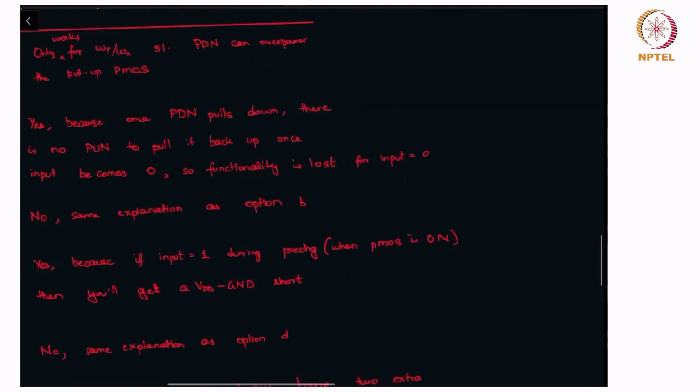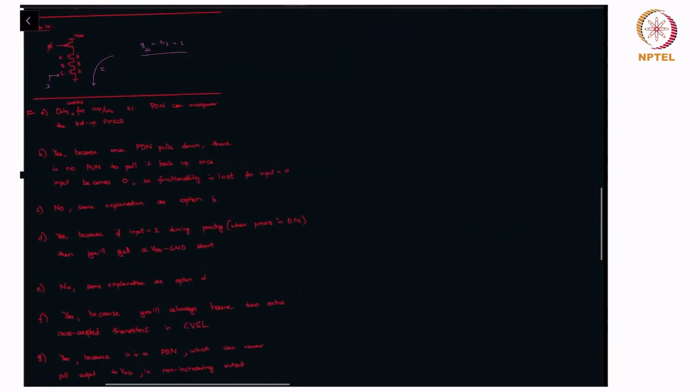Yes, because the idea is that, let's say the input is 1 to a dynamic unfooted inverter. It doesn't matter whether it's footed or unfooted, I'm just giving an example. If the input is 1, the output gets pulled to 0, right? But then if the input were to go to 0, there's nothing pulling it up again, because during the evaluate phase phi is equal to 1, so the PMOS stack is off. So the input is 0 and the output is 0.